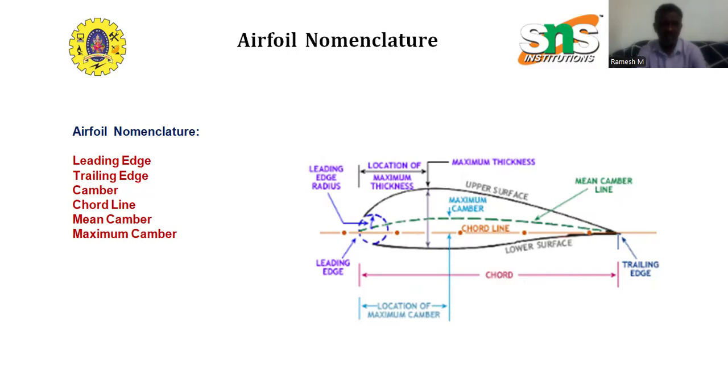The leading edge marks the frontmost point of the airfoil, where it first encounters the oncoming airflow. The shape of the leading edge is a crucial factor and it is tailored to suit the airfoil's intended function. For high-speed airfoils, as found on modern fighter aircraft, the leading edge is razor sharp.